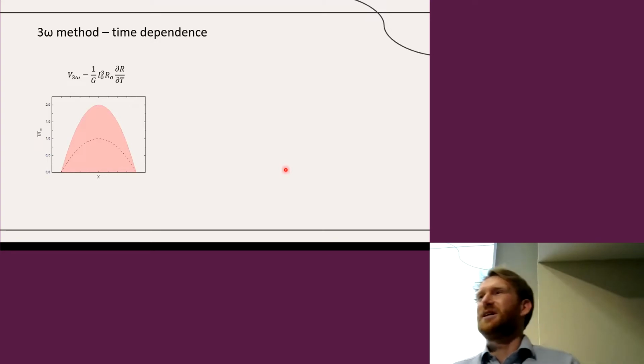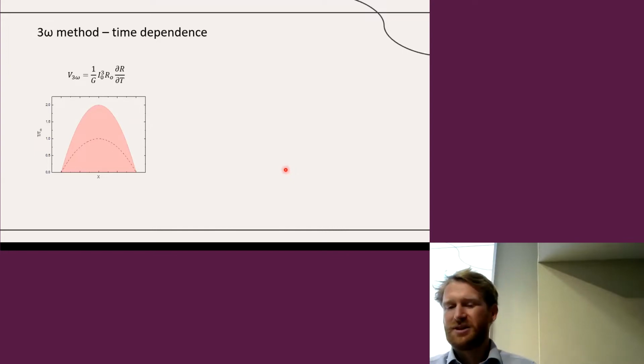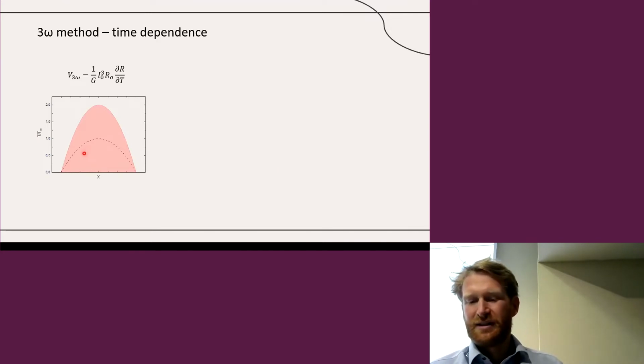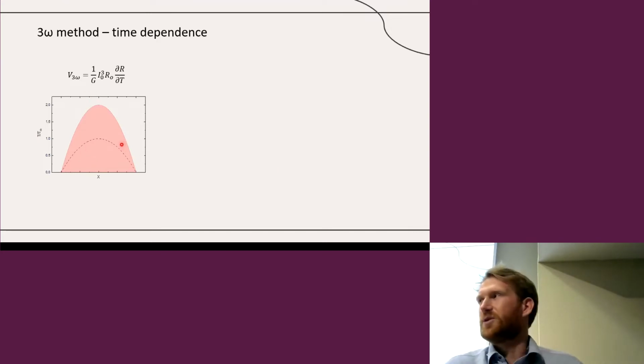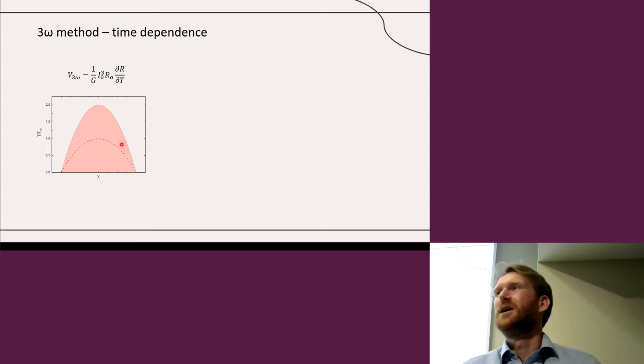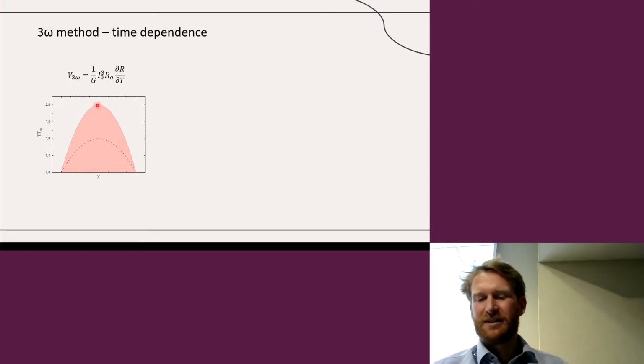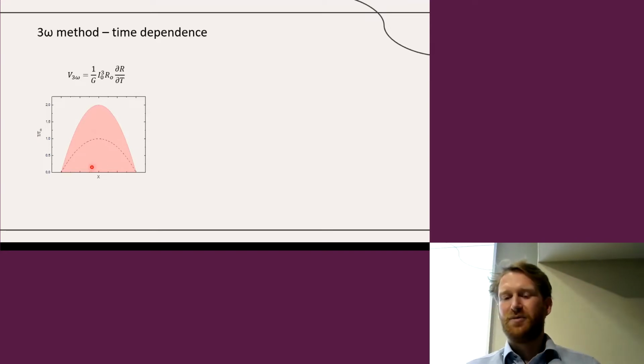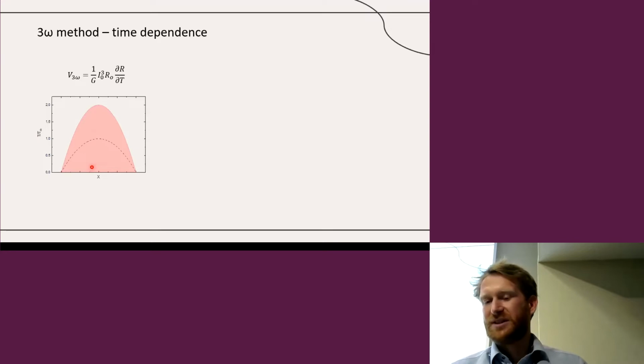So far I assumed steady state. So I said the frequency is very small compared to the typical thermal time constants of the system, the thermal dissipation. So what we get then is essentially that our thermal profile is exactly following our oscillating current. So we see that when our current is maximum, our thermal profile will be maximum as well. And when there's no current, it will reach minimum. So our temperature profile is also continuously fluctuating along with the same frequency.